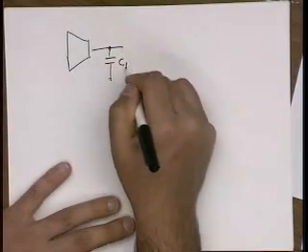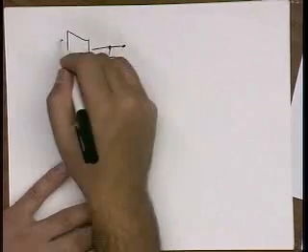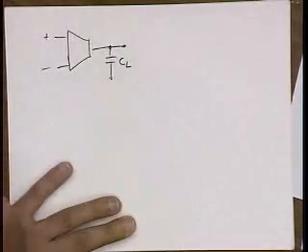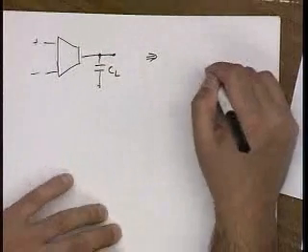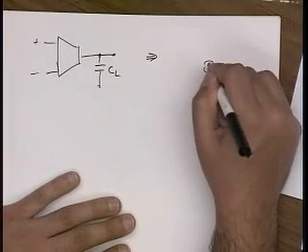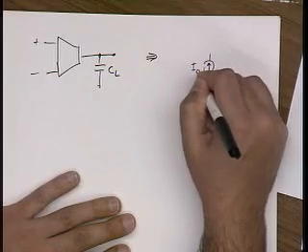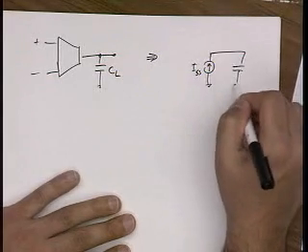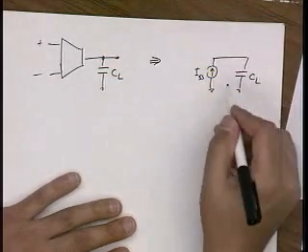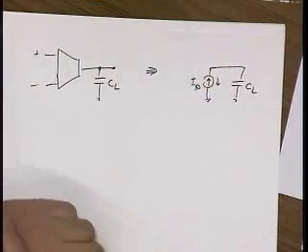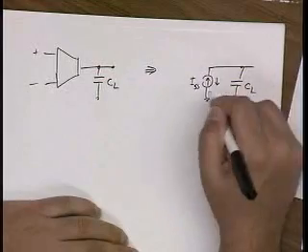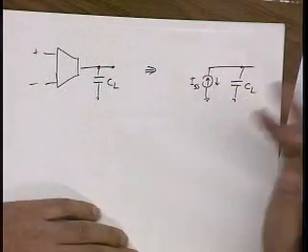In our transconductance amplifier, I have some load capacitance. I apply a big input differential voltage, and then my system just becomes a constant current ISS flowing into CL. This could be plus or minus, depending on the sign of the input. But if I put a constant current into a capacitor, I get a linear ramp.